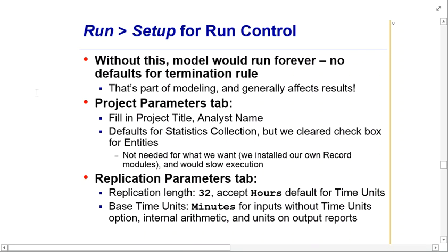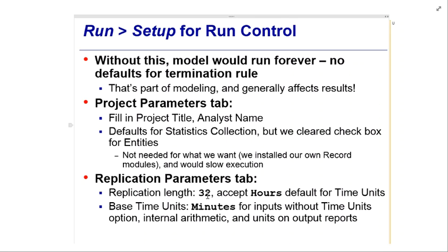So now, again, we're ready to run. We need to go into the setup module. We need to establish our replication parameters. Again, we've got multiple parts coming in, so replication length is probably the easiest way to do that, rather than having a fixed number of parts coming out of each create module, especially because I have 4 coming out of one and 1 coming out of the other. Got to make sure I get those units right. This is just a simpler way to do it, but it doesn't matter. It could be done either way.